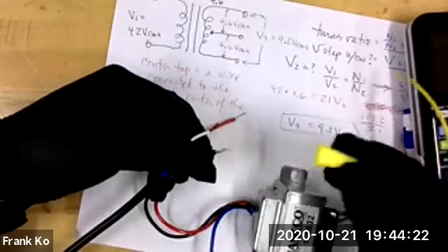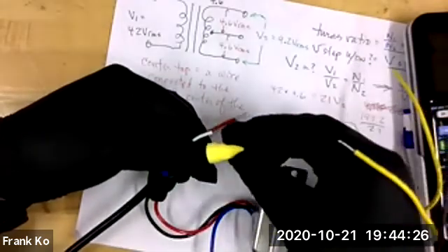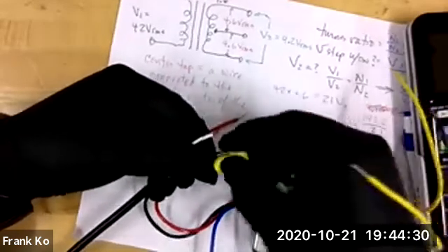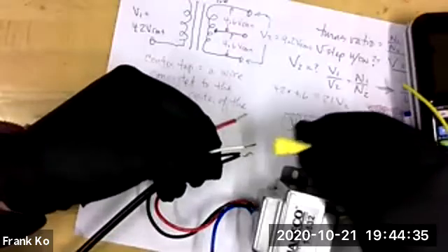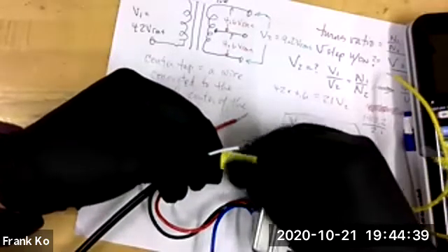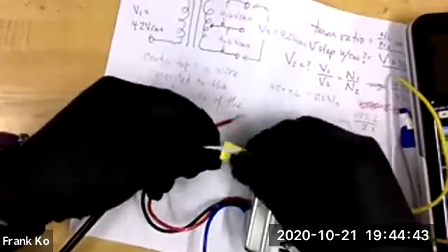And so what you want to do, watch this carefully. While these are twisted together, held with one hand, I'm going to twist on the wire nut over the pair of wires, pushing in. Here we go. I'm going to push in and twist, twist, twist, and steady pressure pushing in while you're twisting.